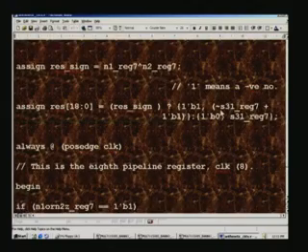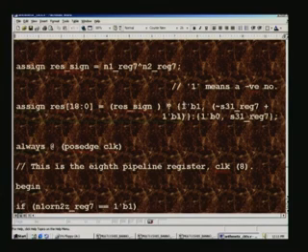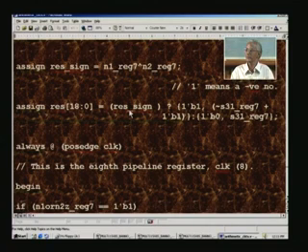So that is what it is. You have to take the 2's complement and also append 1 here, that is the sign bit, if this is for the negative number, so long as this is 1. If it is 0, that is, it is a positive number, what will happen? We have only to take that S31, which is the result, and just add one more bit here, because that was only 18 bits and now the result must be 19 bits. Therefore we append 0 here, implying that this is a positive number.